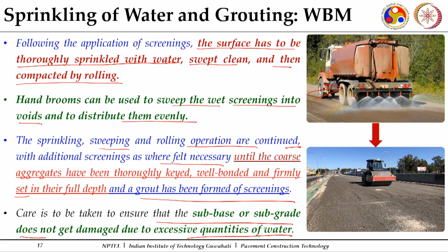This happens if there are no proper water distributors, and you directly open up a pipe and spread it manually. There may be uneven distribution, and that water may go down and hamper your underlying layer, which may be your subgrade or subbase layer. That should not happen.